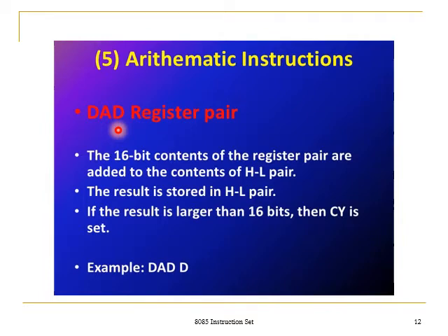So one operand for the DAD instruction will come from the HL register pair, and the other value for addition can come from either of the remaining two register pairs, the BC register pair or the DE register pair. After the arithmetic operation is over, the result is stored in the HL register pair, not in the accumulator, because it is a 16-bit addition.